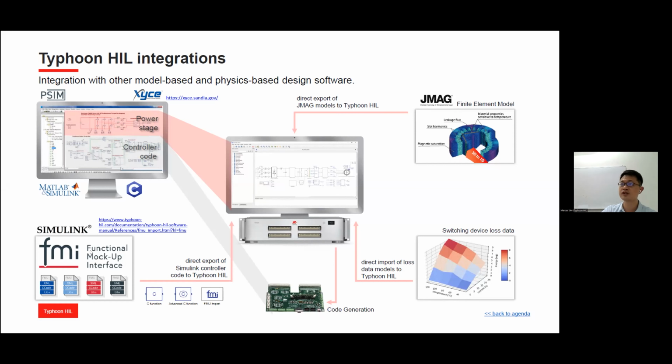It uses a functional mockup interface. I will send the link on the chat group. So after your design in Simulink, you can convert it into FMI, the functional mockup interface, and then you can export the controller code directly to Typhoon HIL itself. So this is one example.